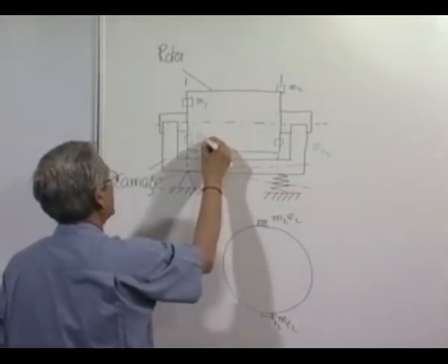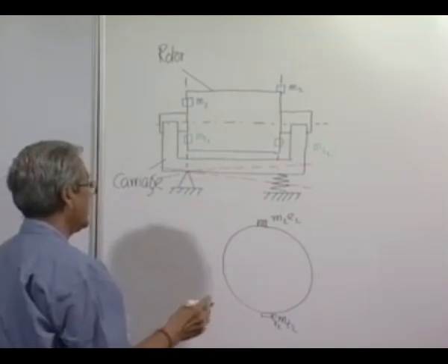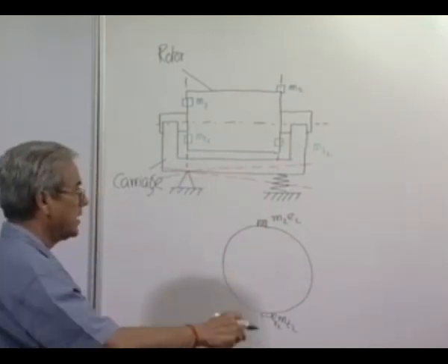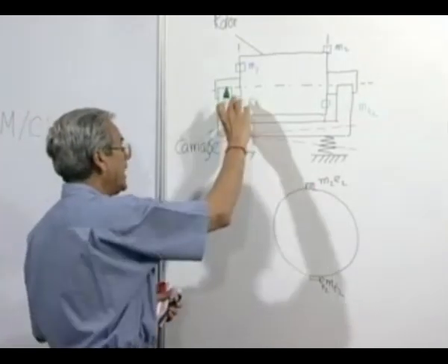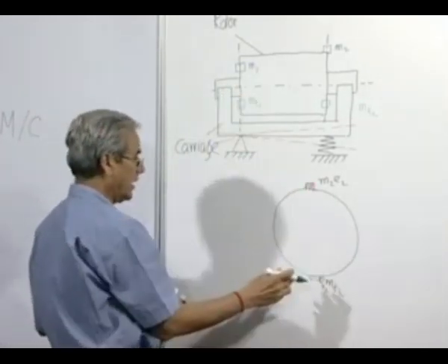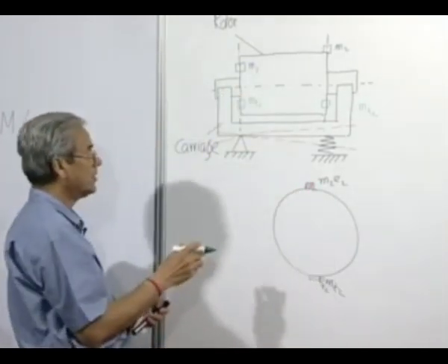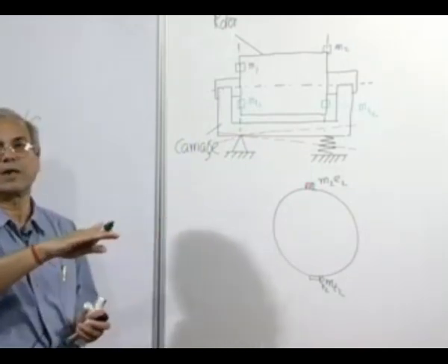So, we start with balancing or trial mass MT1. We first see at which angular position this produces minimum oscillation, and then we adjust the product MT1 and U1, so that the vibration almost vanishes.